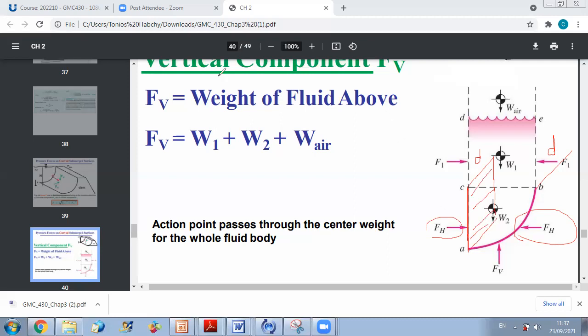And we have developed together how to find the force acting on a flat surface. So the advantage here is that you can use all formulas developed before to get F_H, because all you have to do is find the action of water on this vertical rectangular surface, and say that this will be equivalent to the horizontal component of the force acting on the fluid from the curved form. Any question on how we determined F horizontal?